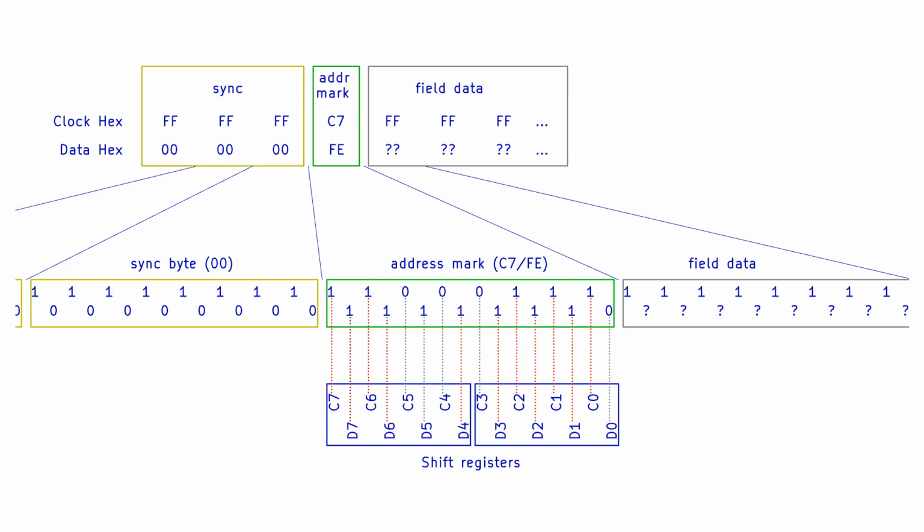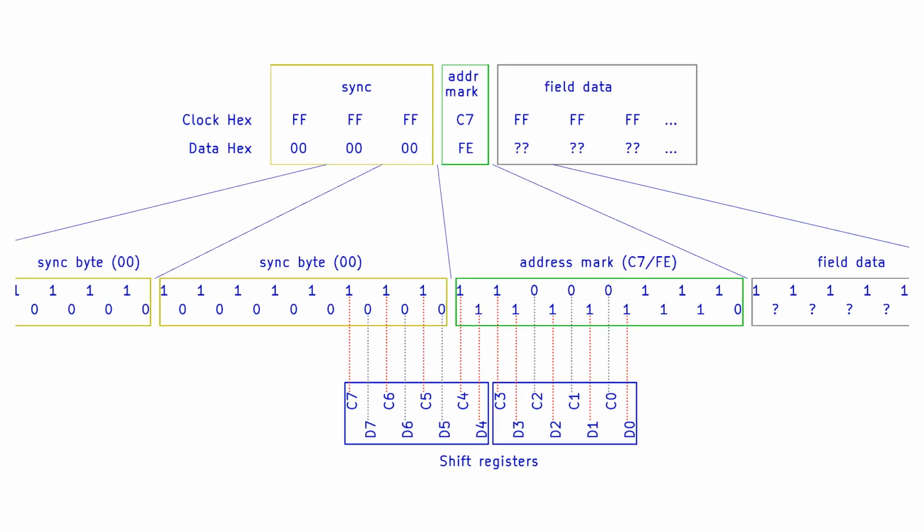I don't really want to do that in an electronic circuit because every bit I compare costs me real estate on the breadboard. So what I'm going to do is use an alternate mechanism that I've thought of, which will reduce the amount of bits I actually need to compare, while still retaining enough confidence that what I've found is actually a valid address mark. I'm going to make a circuit which just looks for those 3 missing clock bits and 1 of the missing data bits of the preceding 0 bytes. And that should be enough for me to fairly confidently identify the starts of these address marks.